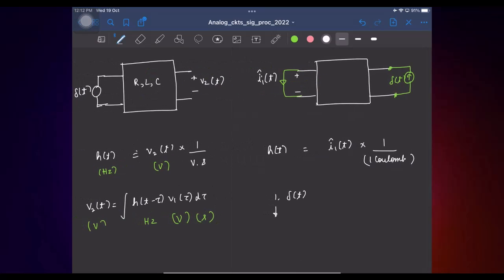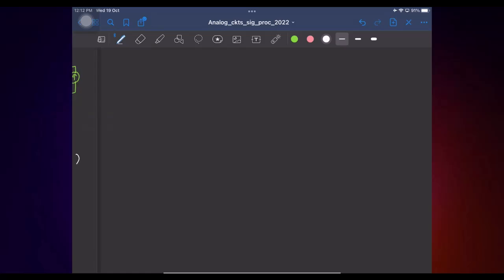So this is with respect to RLC. Now we saw that if the network also has controlled sources, the reciprocity will not be valid. So for interreciprocity, what do we have to do? We need to find a network which we call the adjoint network. In the adjoint network, if in the original network we had R, L and C in a particular branch, we don't change anything.